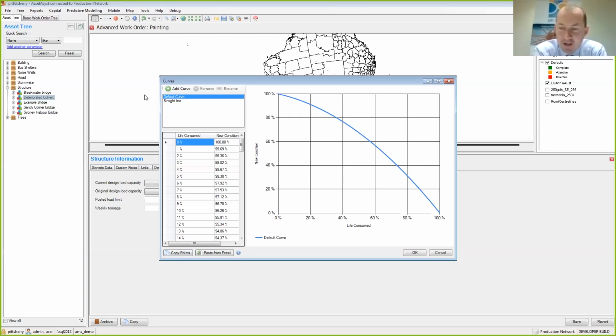That gets to the third way at the moment, which is rather than fitting data to points and perhaps using the wrong cause and effect for it, saying that observation can forecast it, which could be the wrong premise, we can actually use our engineering judgment about a design standard saying something will last a certain amount of time, and then use that knowledge of how long the code would say it should last in that condition, together with our understanding of what condition we see it move through over time, basically.